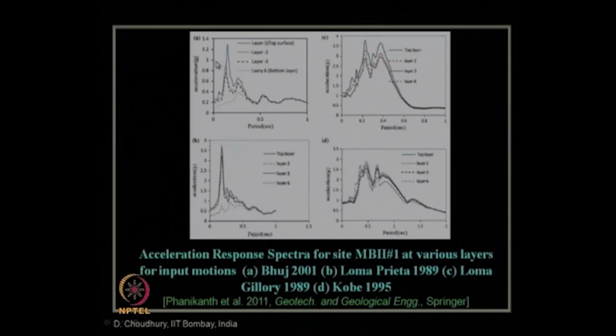Not only that, if we are putting the foundation at a particular layer, we have to design for that particular period and spectral acceleration corresponding to different layers with respect to different input earthquake motions. This is very important for a detailed study at a particular site, which will not be available in any code, because this is a site-specific ground response analysis.